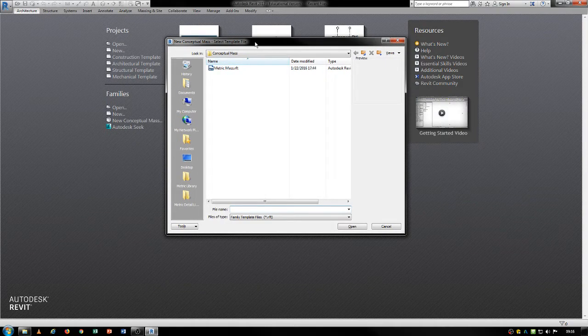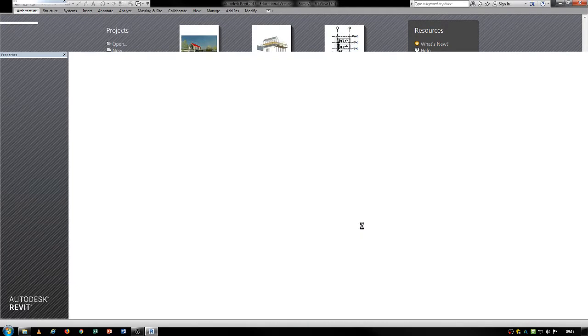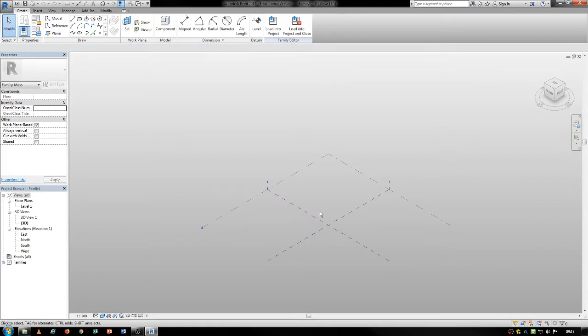changing. But usually when you are doing a massing or a form thing, it's better to be in your conceptual massing environment because there are reference points and other things available to you that may not be available in an architectural Revit project. And for that reason, if you define a point in Dynamo and you want to bring it into your Revit, it's better to have an environment that is built for that.